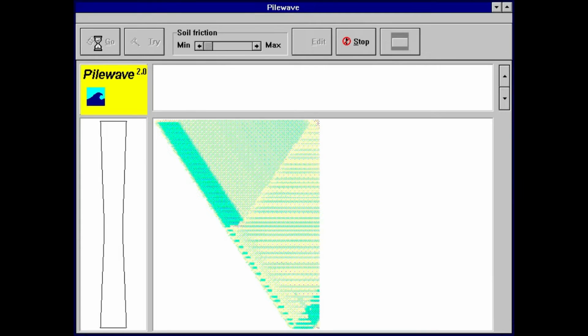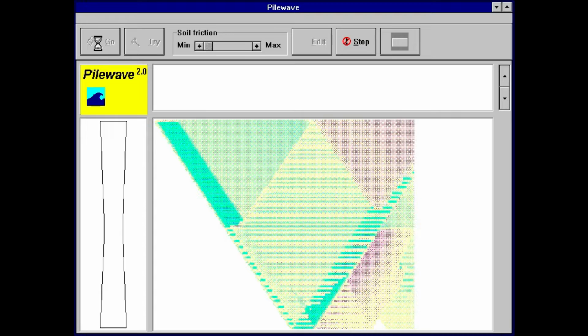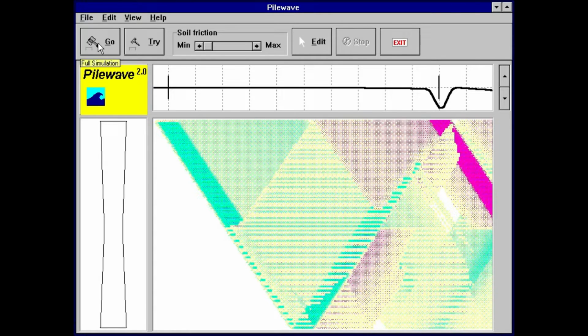If you get a drill shaft, for example, that has a continuous taper, you get the same problem you have with wood piles. You're going to get a lot of different reflections back to the surface. And then about here in the middle, you get a major return. All of a sudden you start getting different transmissions of the compression wave and different reflections.